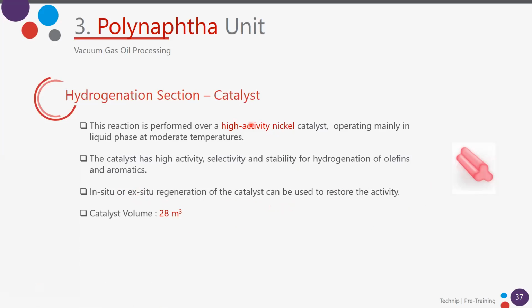Okay, so it is a nickel catalyst, high activity nickel catalyst. It's high activity, selectivity, and stability. And we use this volume. We can have a regeneration in situ, or we can have it outside the unit, okay, to restore the activity as the catalyst goes through the time and gets deactivated.